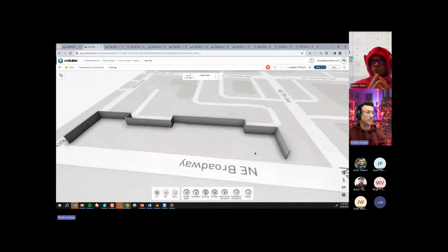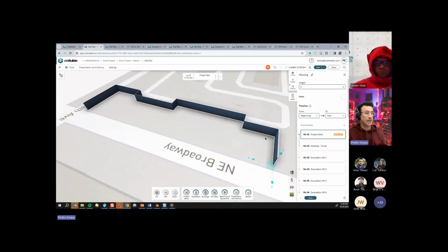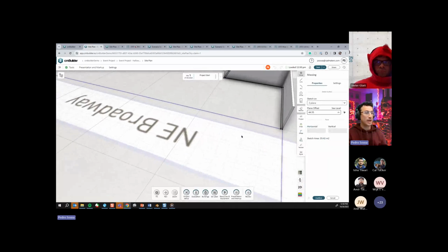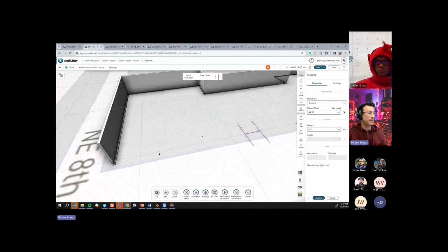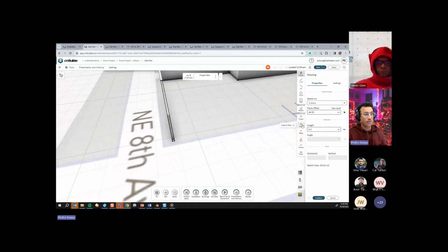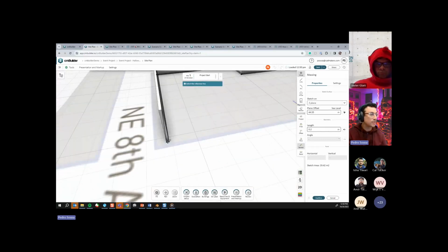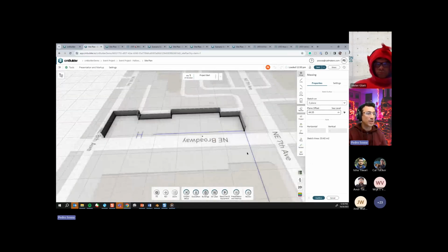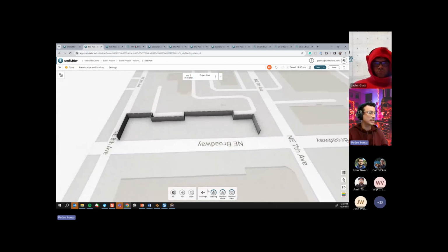Cool. So let's say that I want to create another wall over here to finish this one. I can go and edit my sketch. I want to make this wall over here snap to this line. So I'm going to select that line, click on the snapping function. Well, actually, it has to be parallel to this other line. So now they are sharing the same face. And I just need to create a new massing that will close that end part.